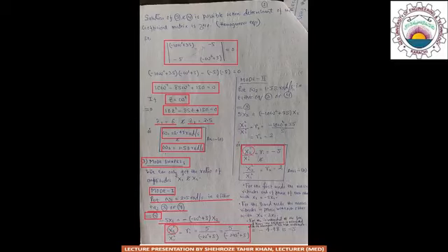where x12 denotes the mode shape of the second mass at the first natural frequency, and x11 denotes the mode shape of the first mass at the first natural frequency. The ratio of these two mode shapes is equal to minus 5, where the minus sign indicates that these two mode shapes are out of phase with each other and their ratio is equal to 5.